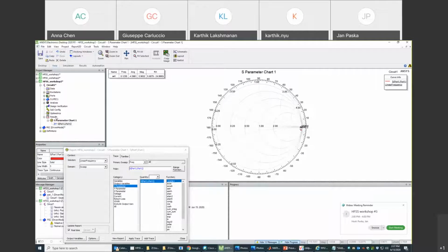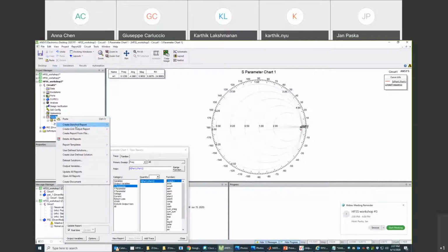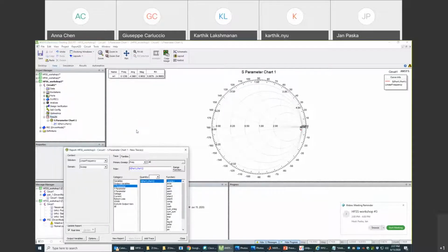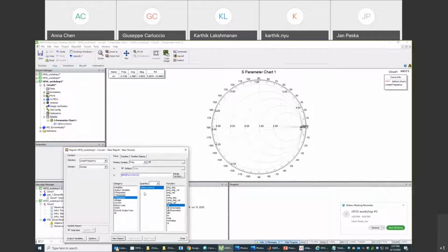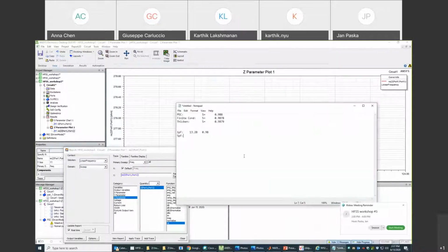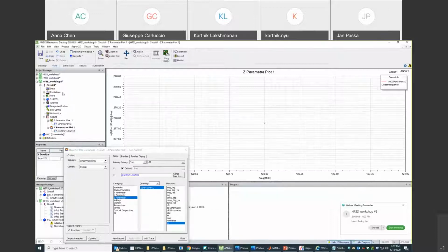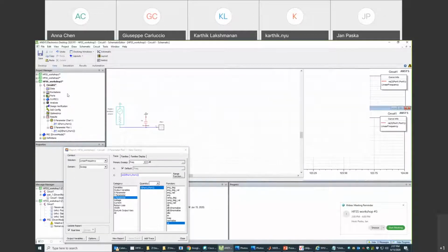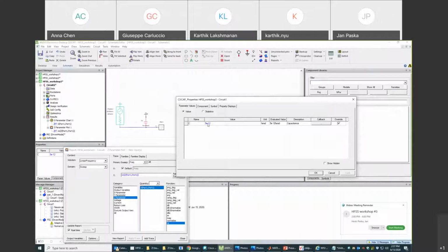Actually, what we should be looking at is the real part of the impedance. Let's just do that. Real part. And the real part is 278, but we know that we overshot. 278, and we don't know the real part for 1 picofarad. What happens if we do 3 picofarad here.